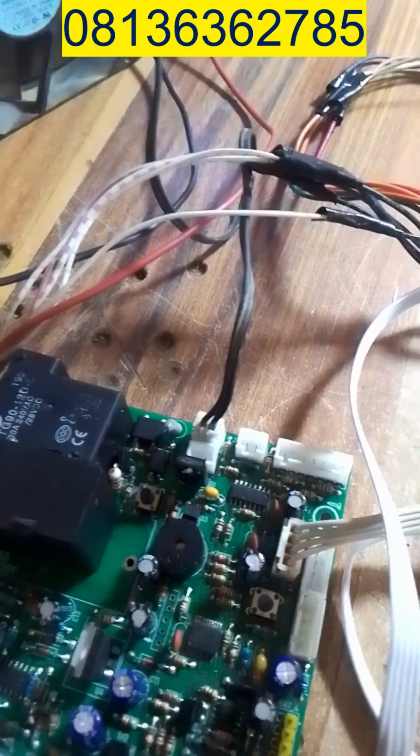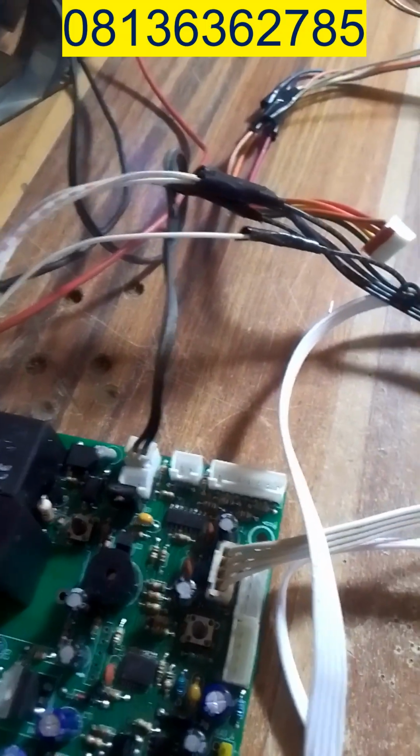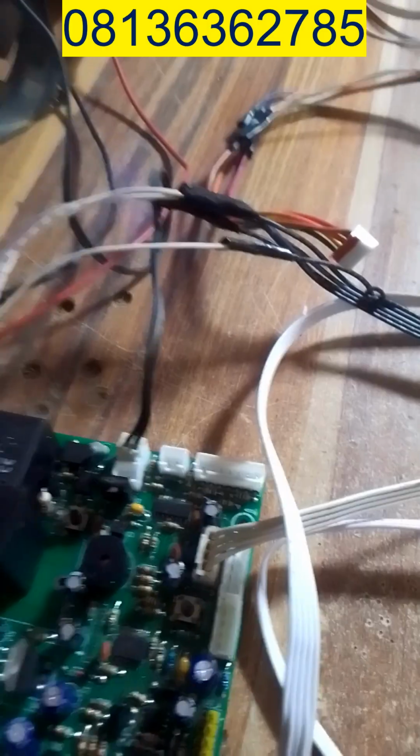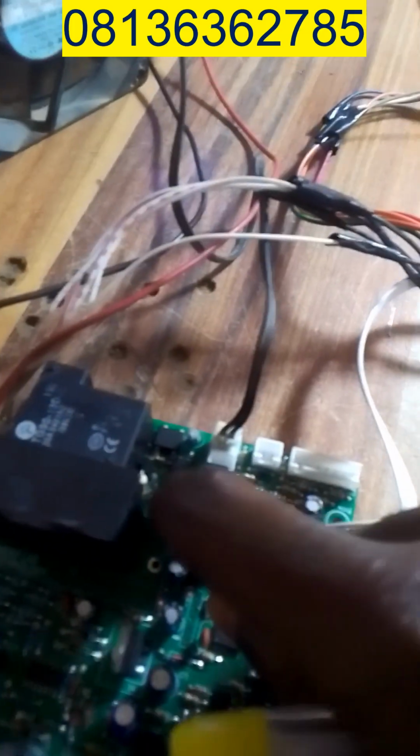This same button, but it's a short press. To change the LCD, it is a long press. You hold it down until you hear an alarm, a sound. But if you are changing the voltage, you just press it subtly. Then the voltage here will change. So let me press it here now and observe the voltage. I've pressed it. Then I will come in and observe it.